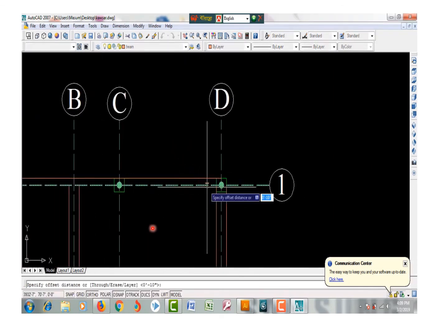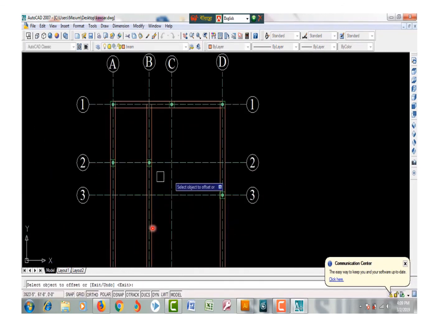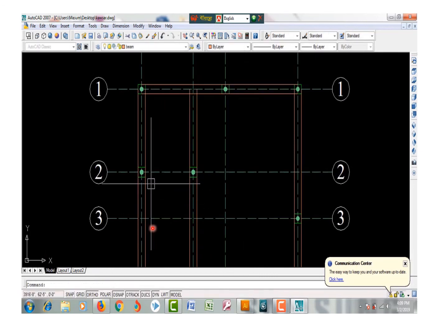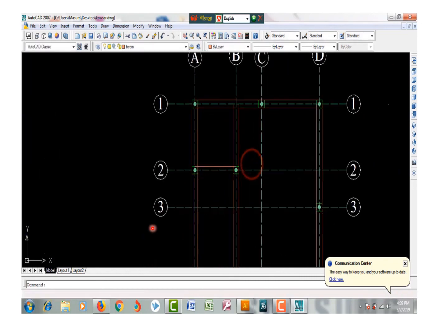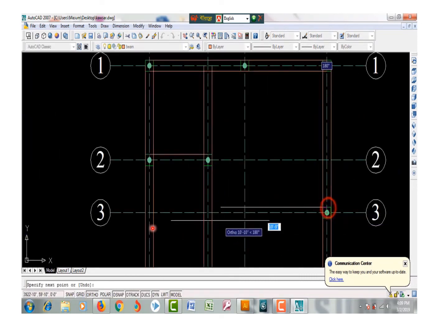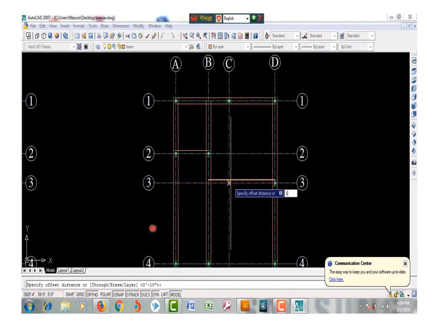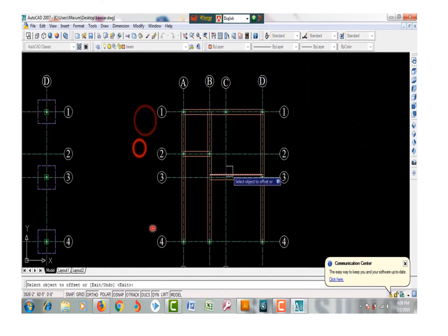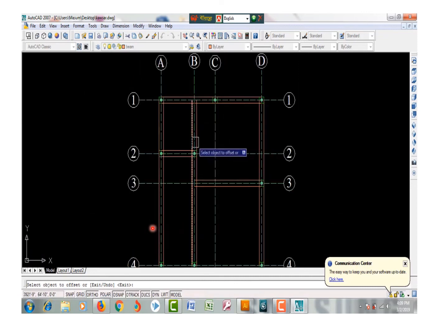And the major arrangement, in order to reduce the eccentricity, is that the center width of my beam can be kept as the width of my column in which the beam is connecting, so that the packing of reinforcements, the flowing of reinforcement, everything will be uniformly distributed between beam to beam and column to column, and mostly by beam to column joints also. So now I made all beams to connect together. Same way I am doing it for the transverse axis also.